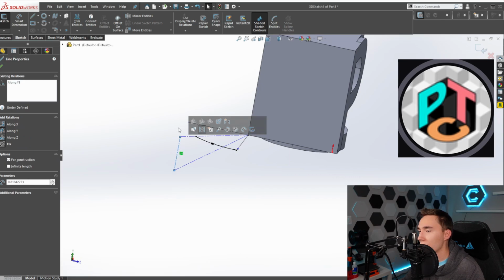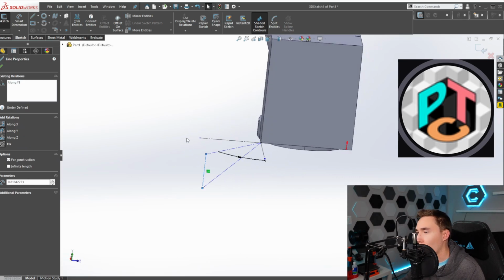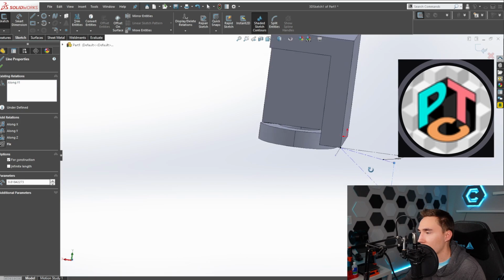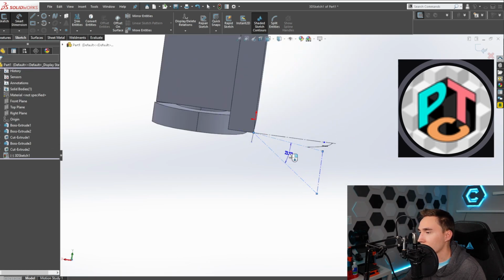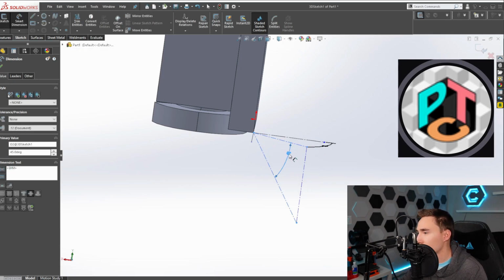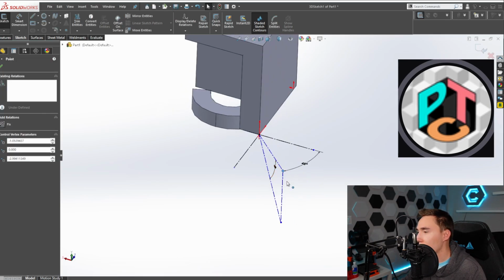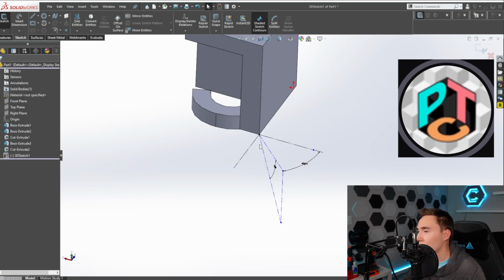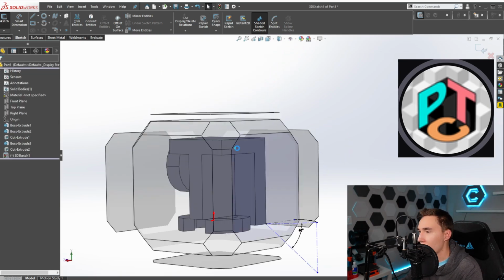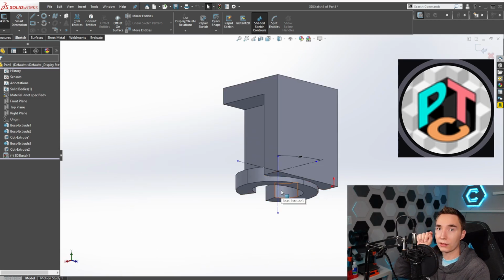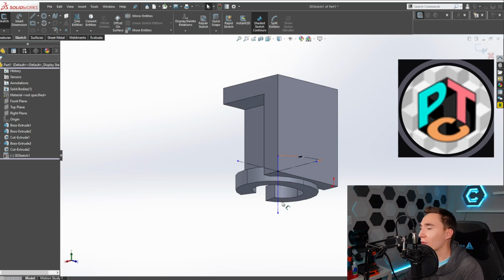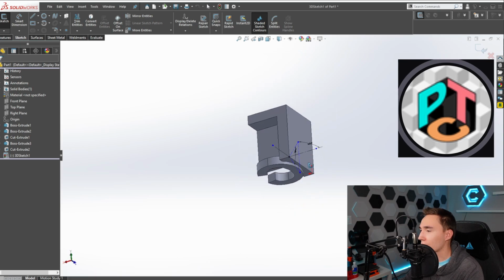So now this one we made sure was in the Y plane only, so it's going straight up and down. All we need to do now is make this a 45, and we should have a perfectly 45, 45, 45, same as this view right here. And that looks perfect. Looks like we're looking straight on to that. I always move my head to look at it. We look like we're looking straight onto that arrow, which is exactly what we want.